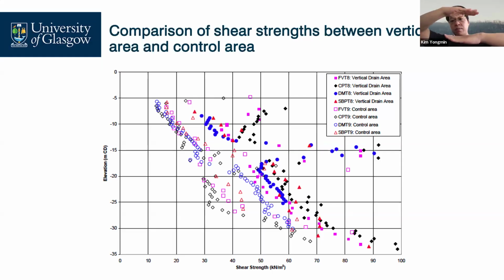Before, the marine clay soil layer is quite soft. When you step on this, your foot probably gets stuck in the clay layer because it is very soft and loose. And after consolidation, this clay layer squeezes out water and is densely packed.